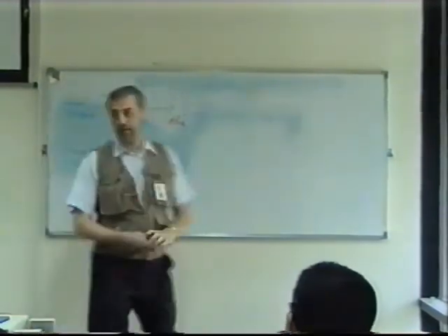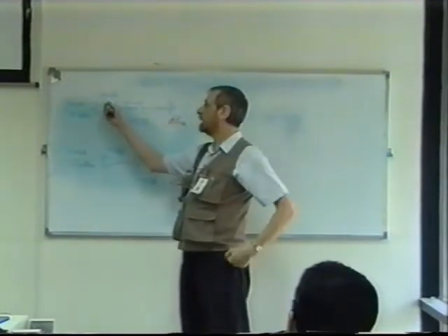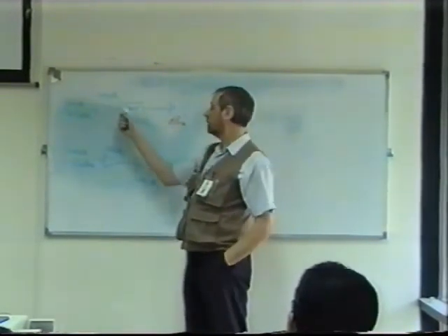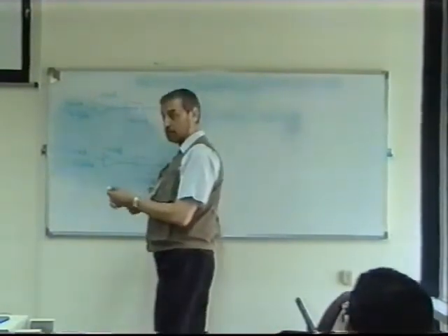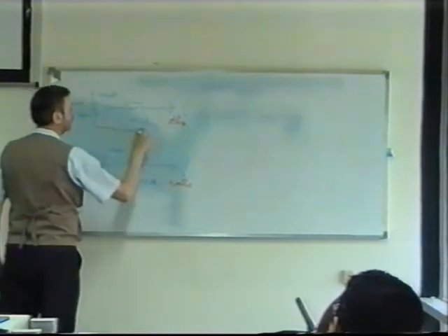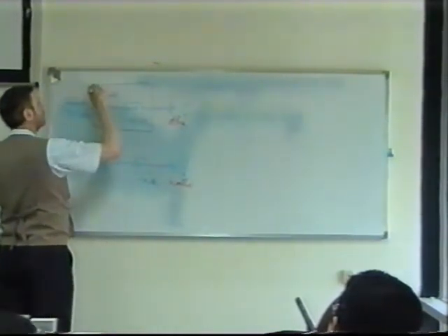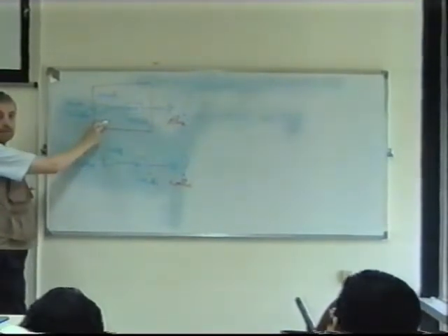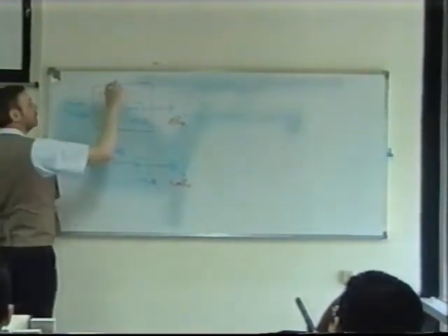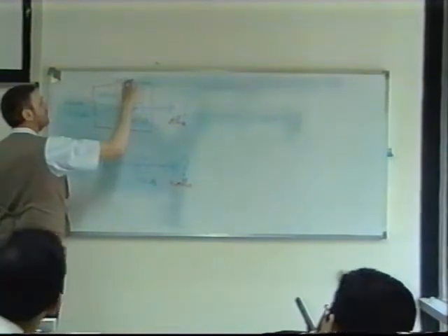Because look at what we've got to go through. We have an amplifier with a gain of 100 dBs, followed by an attenuator with a gain of minus 60 dBs. Now what you can do, you can look at these two as one unit with one particular gain. What's the gain going to be? 40 dB. Yes. That's a ratio of 10,000. This now brings out one of the advantages of using logarithms like this.